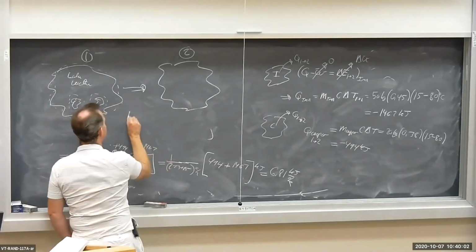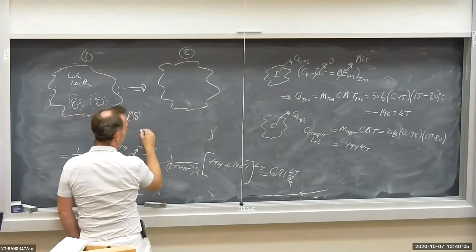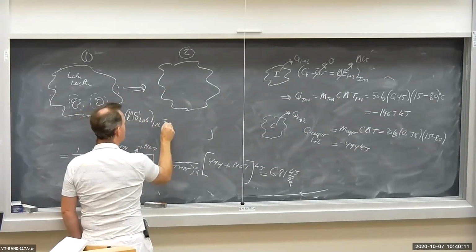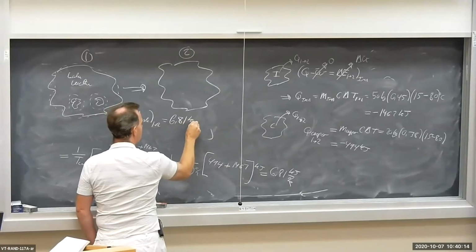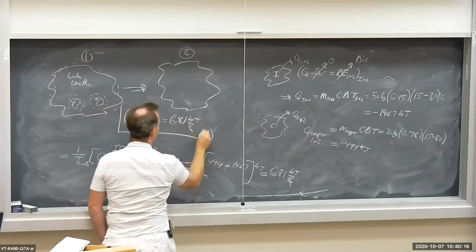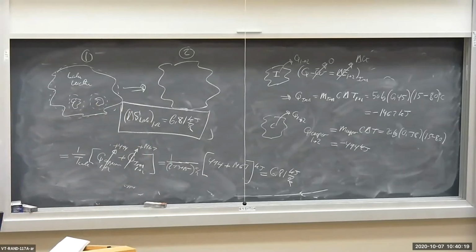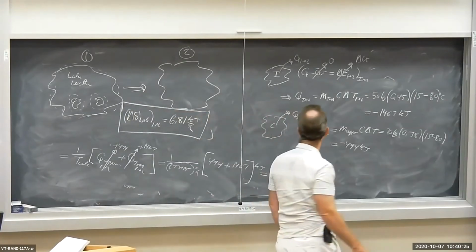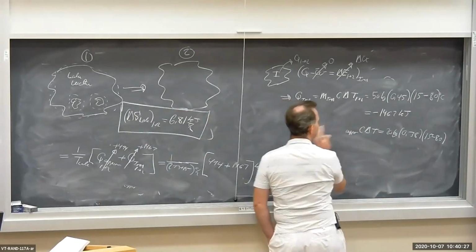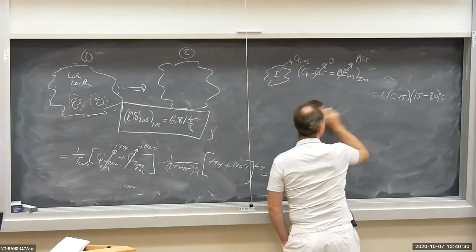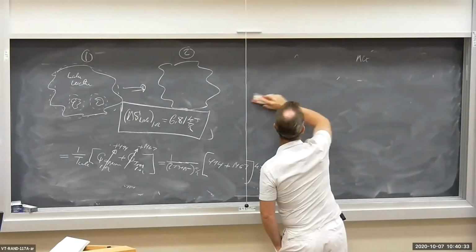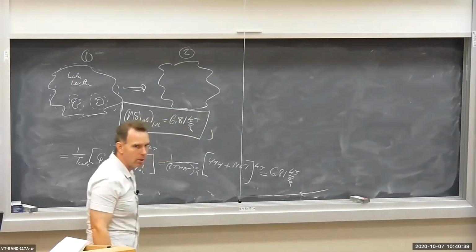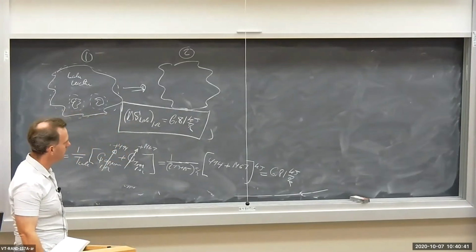So delta S for the lake water is 6.81 kilojoule per degree Kelvin. Let's box that up. Okay? Had to go through and use the energy balance on the solids. Again, no work because there's no change in volume. Solids are incompressible. No change in kinetic and potential energies, therefore Q is equal to delta U.